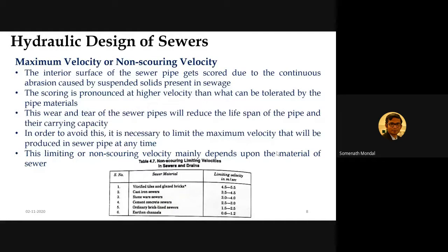But here you just remember that it is an appurtenance which facilitates changes in the head or the elevation without causing significant damage or abrasion to the sewer's internal surface. So this is the way, in the hilly region, the extra available gradient is taken care of.